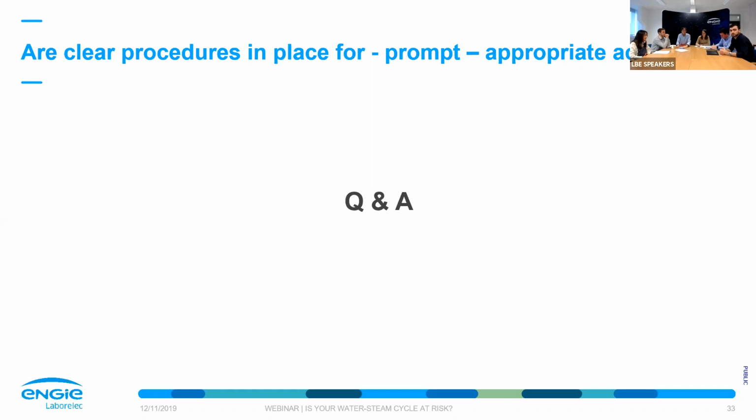So we really recommend to automate your condenser leakage detection, and that at least an online analyzer is installed, because from the moment that you have a condenser leakage, you start corroding your system. So you have to react immediately, and you can never do it by offline analysis. You will always be too late, in fact. And the cation conductivity is also a good solution if you don't have a sodium analyzer. It's less sensitive than a sodium analyzer, but it will work indeed.